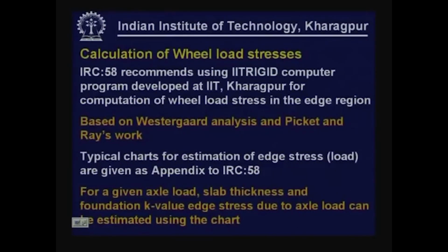For calculation of wheel load stresses, Indian Roads Congress 58 2002 guidelines recommend use of the IITRIGID computer program developed at IIT Kharagpur for computation of wheel load stresses in the edge region. As identified already, the edge region is considered to be the critical region as far as the wheel loads are concerned.